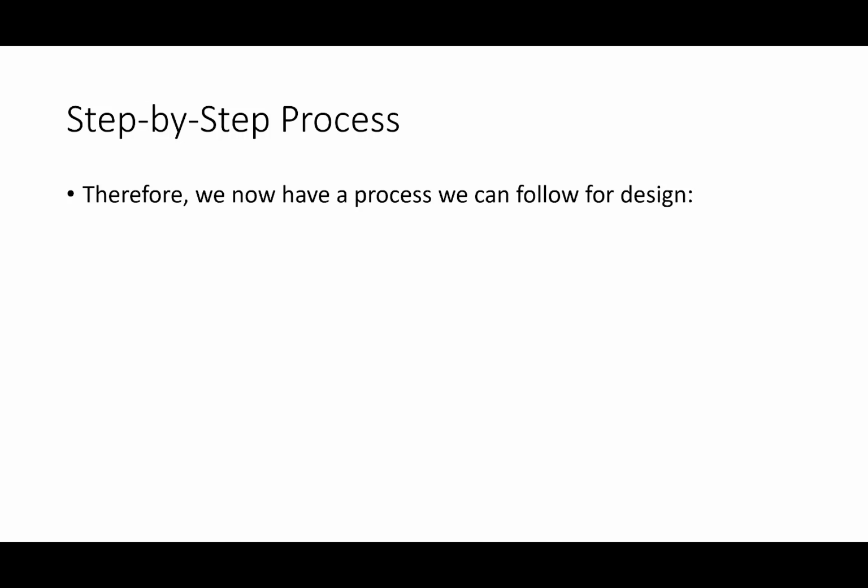So let's go through a step-by-step process. And to be clear, I don't really think there's anything hyper-inventive about this process. I think you probably could come up with this process yourself right now. If you were designing a member to withstand a given set of loads, what do you think is the first thing you need to do? Like if I give you a member and I say, I want you to design it for a dead load of 80 kips and a live load of 150 kips, what do you think the first thing you need to do is?